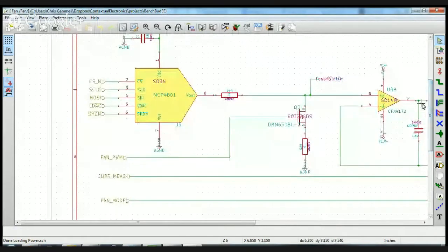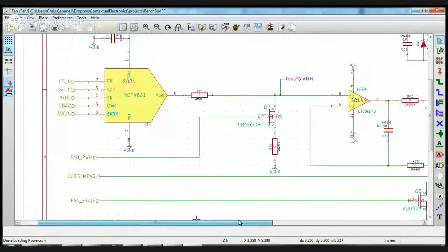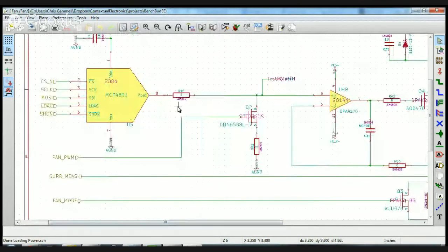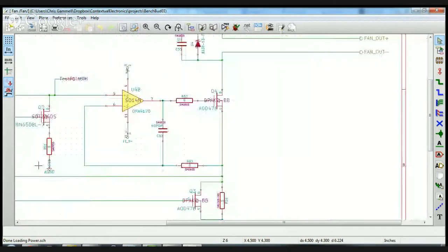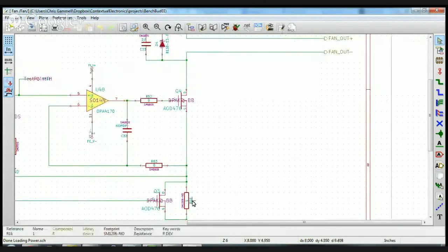We had talked about that at one point, possibly doing this as an optional divider here. But I think ultimately what will happen is an enhancement will need to change. So we have the gain that can go up to 4 volts here, right? And if we want 4 volts here, we want a little bit more fine control. We'll actually change this resistor here. The only downside is I think I misspoke when I talked about that. I think I said that we would go less. No, that is less, right?